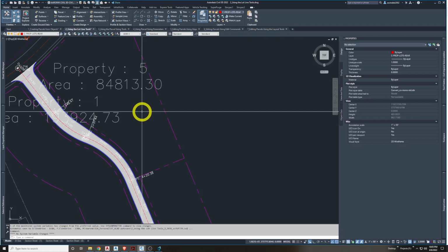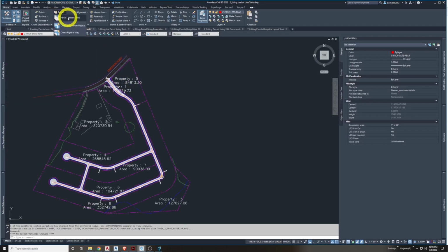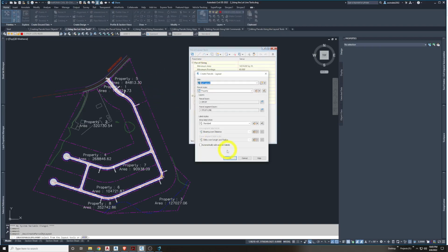And now we're going to make another parcel. So let's go back here, zoom out a little, and go to Parcel, Create Parcel creation tools. And now we're going to go to a different area and click Draw Tangent, right here. Draw Tangent with no curves. This is going to be smart enough, if we click that, to go to the outer extents of the property we made, and then make its own little parcel, but with no curves inside of it.